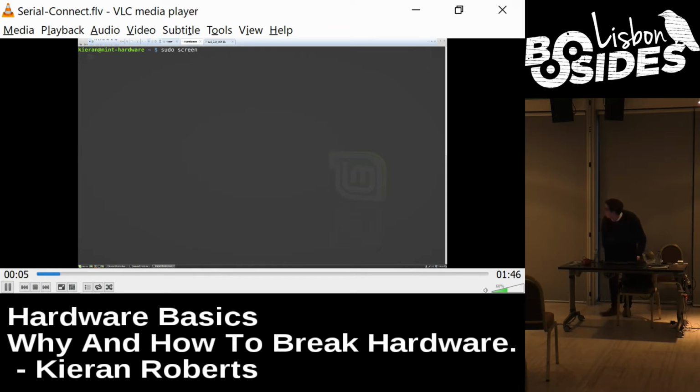Okay, that's fine. So we're just going to use a screen command, tell it which device we're pointing at. That is this USB serial converter. And you're going to have your TX pin on here wired to the RX pin on the device and vice versa. And we're going to set the baud rate, which kind of flashed away pretty quick there. The baud rate is just the frequency, the speed at which you're going to speak to the device.